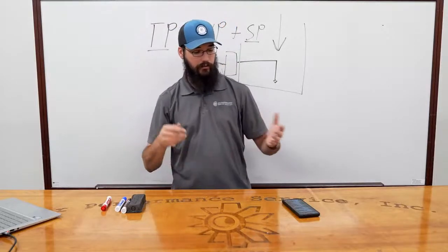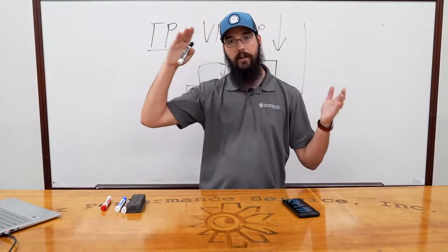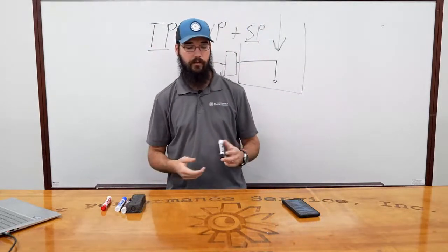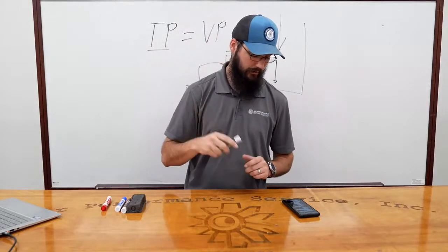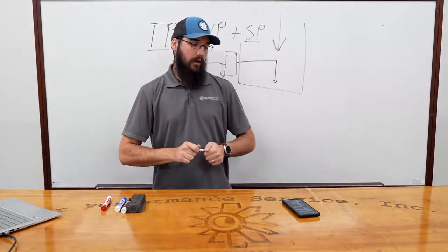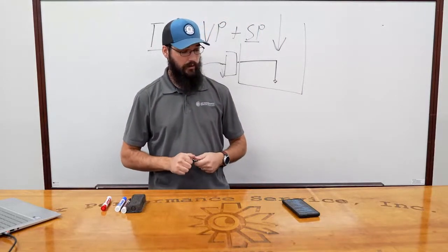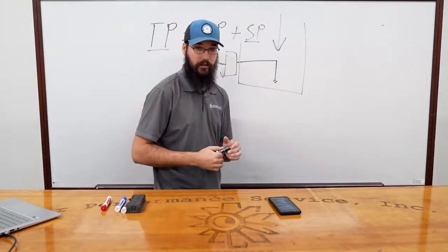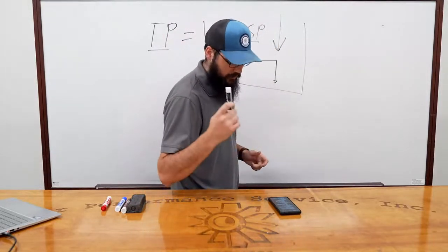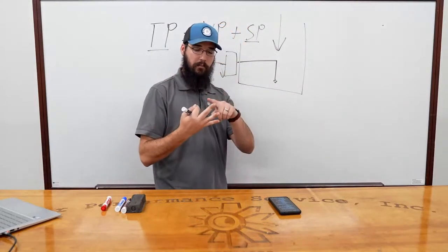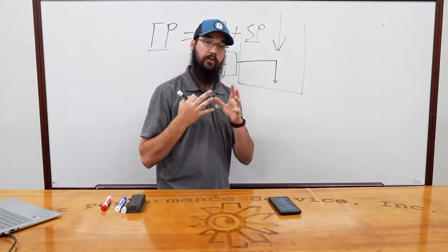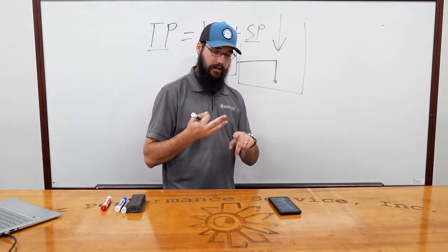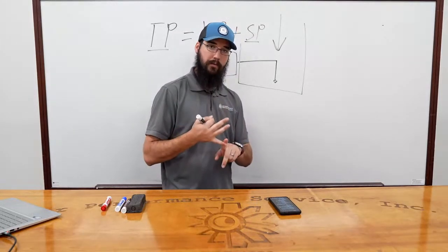In our particular case, I'm just going to keep it simple: most of the time you're going to have external static as an option, especially working in the commercial space like we do, because we don't run into that many regular furnaces sitting on the floor. It's just not as common. A lot of times we have a lot of RTUs. So that's your three main methods or types of ways to measure airflow: the CFM, your static, and then your feet per minute.